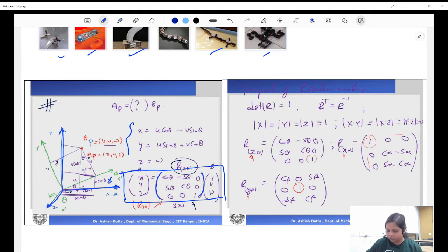The crux of what I'm saying here is that RZ, RY, and RX are given by this. It's all a combination of sine and cos. Once you make the derivation, you will not even have to remember it, you will always get it. You should always be able to write these rotation matrices and map the points from a fixed axis coordinate system to any other rotated axis system.